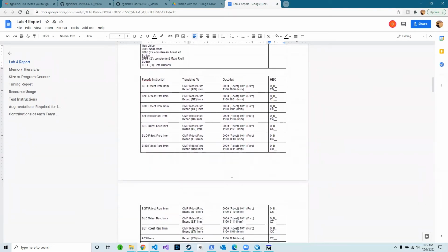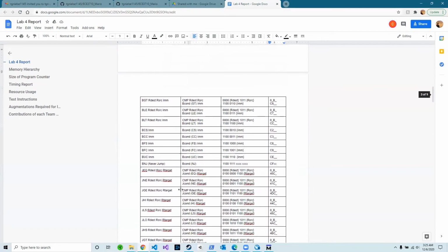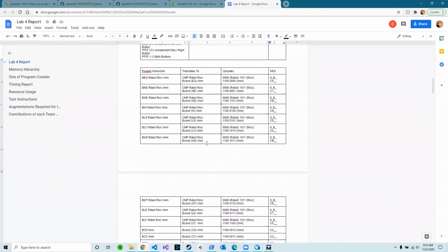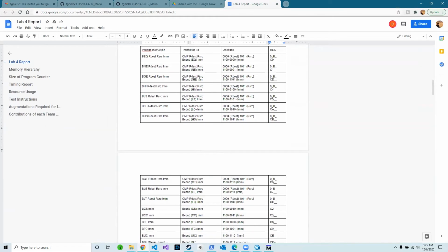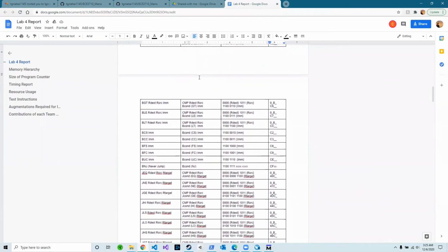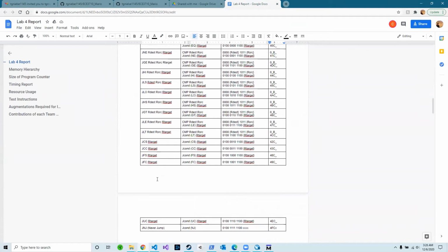But one thing to note is that for our branch and jump instructions, most of them we consider to be pseudo instructions. They're technically just two instructions that we combine into one. For most of the branching and the jumps that deal with conditions, we do the compare instruction first, and then do the actual branch or jump command immediately following it. But for ease of writing and looking at the code, we just combined them into one instruction, which makes writing our code a lot easier.